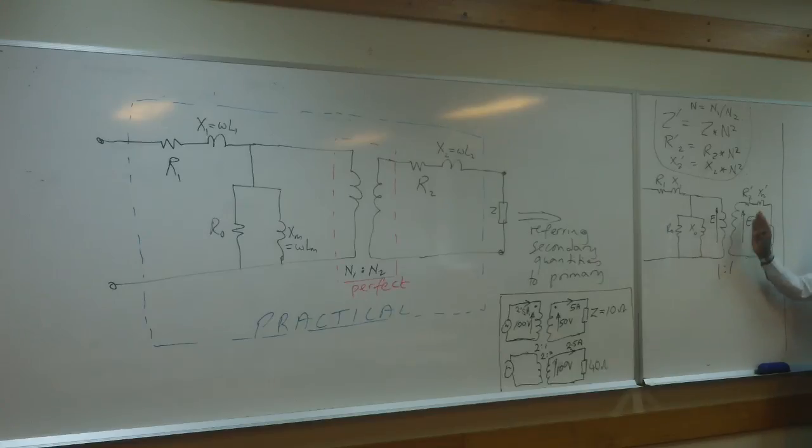This transformer being 1-to-1 means the voltages are not only equal in magnitude, but also equal in phase. Some people might say, oh, they may be 180 out of phase. That's possible. It all depends which one you're using as your reference terminal. But we have defined it. If you want the exact representation, you put a dot there, meaning that both are pointing towards a dot, and therefore they are in phase.